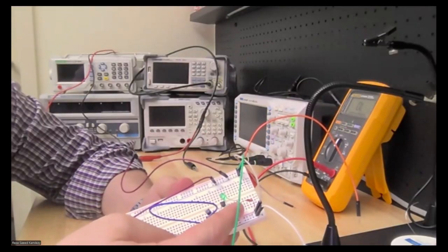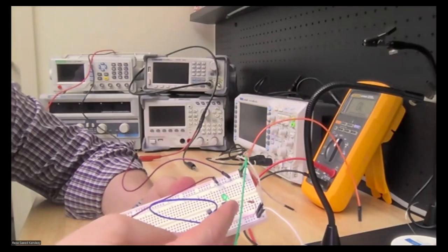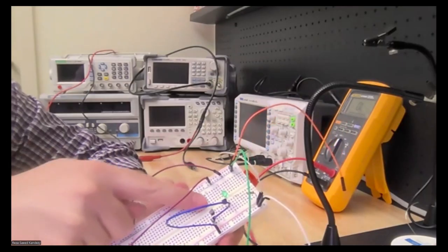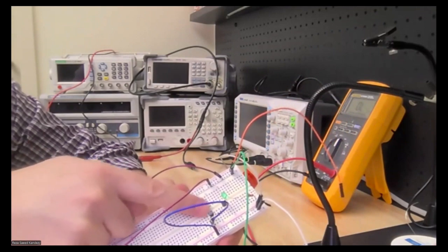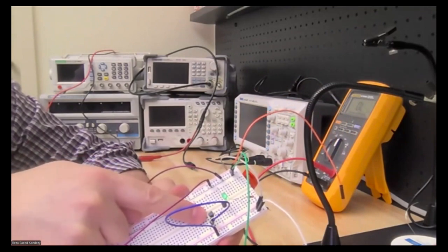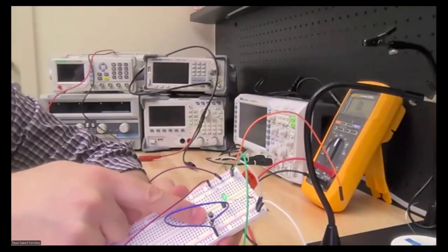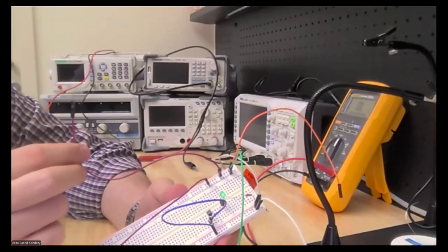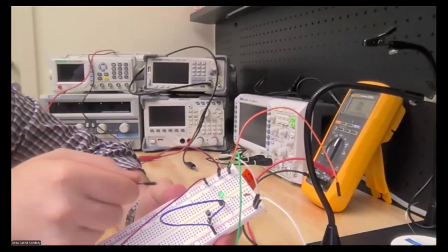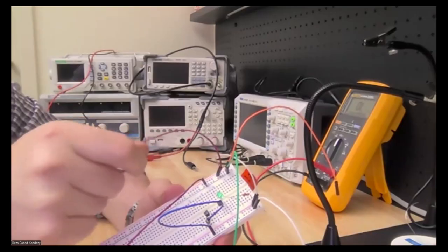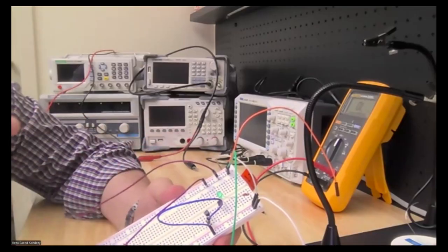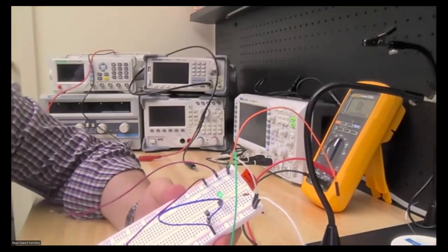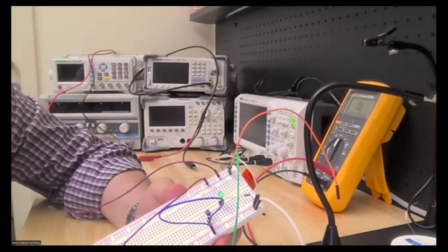There is a resistor in series with the LED, and we have the AND logic block, which is two MOSFETs connected in series. Okay, and I'm going to use two jumper wires to trigger each of the gates. So we have a switch on and off. You can use actual switches, so it's going to be prettier.